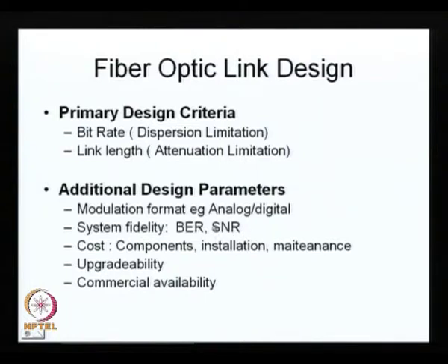In addition to that, for an analog system, we also require the knowledge of what is called the intermodulation products. So, it is not only that the signal should remain above the noise, but the signal should not get distorted, because if the signal gets distorted, essentially it generates certain frequencies, and these frequencies may lie in the neighboring bands and can create interference.